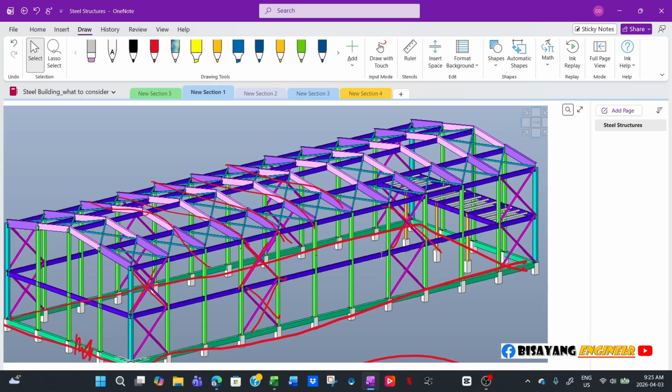For example, the structure is supposed to be just an assembly without regular loading, without the equipment. They would use 100 PSF, but in practice they will design it for 200. It depends on the type of structure.